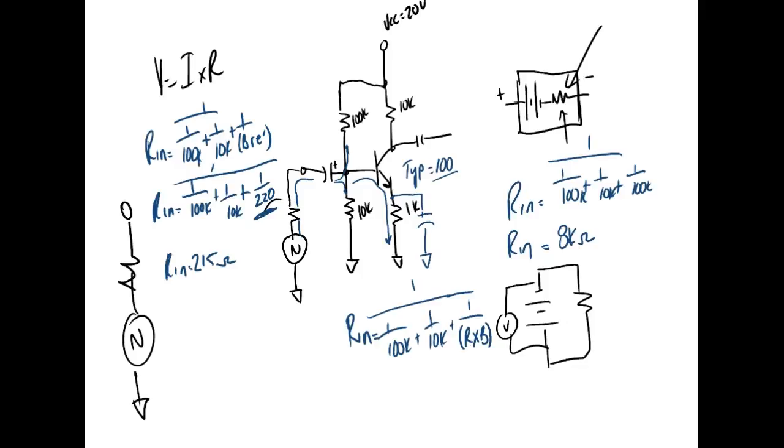You can see why when you look at the schematics on stereo amplifiers, they go through stages. First, we want a little bit of gain, but we want a high input resistance. Then we're going to start dropping the input resistance down, because we're going to get gain out of these transistors. So 3, 4, 5 stages of amplification. I can show you all this transistor wise.